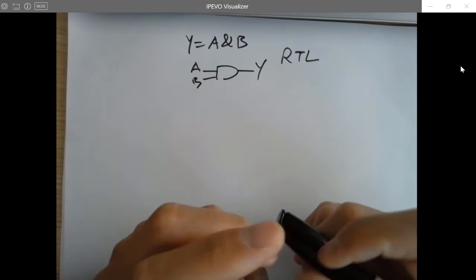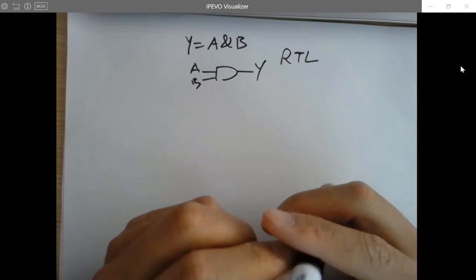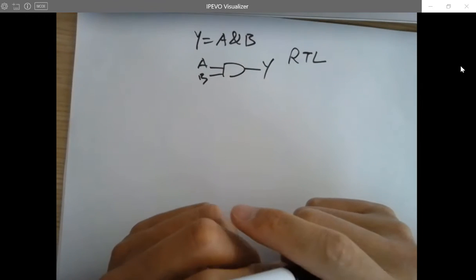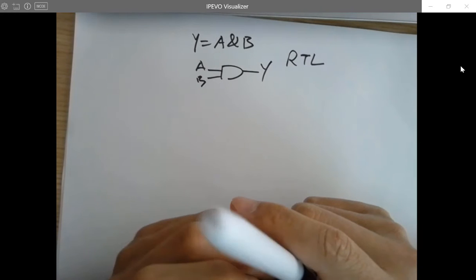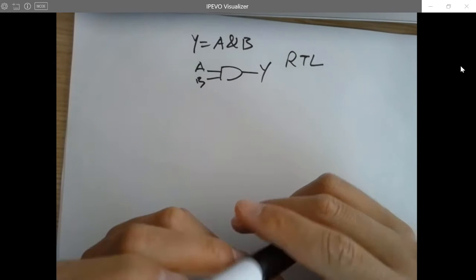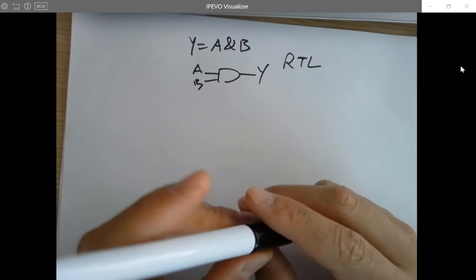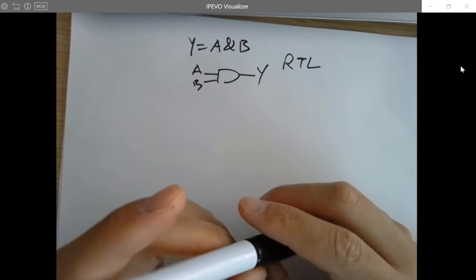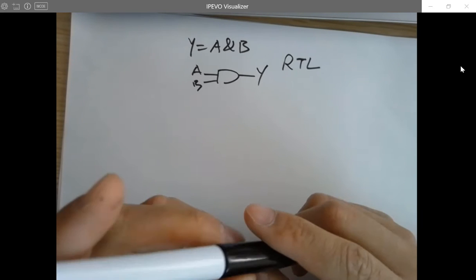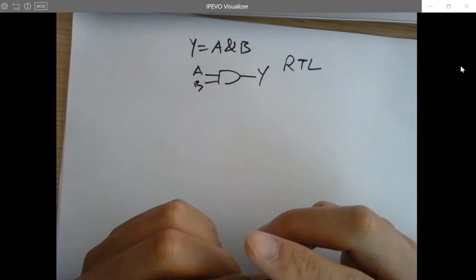So you can see on the ESP chip you have used, it has a little metal cover. If you remove the cover, you can see there are multiple chips. It's not one microcontroller. So the microcontroller is the microcontroller, you can see it. But also there are several other chips. Except for the resistors and capacitors, there's another big IC, which is the flash, and it's the SPI flash. Which means it's communicating with the CPU through SPI, using the flash through SPI.